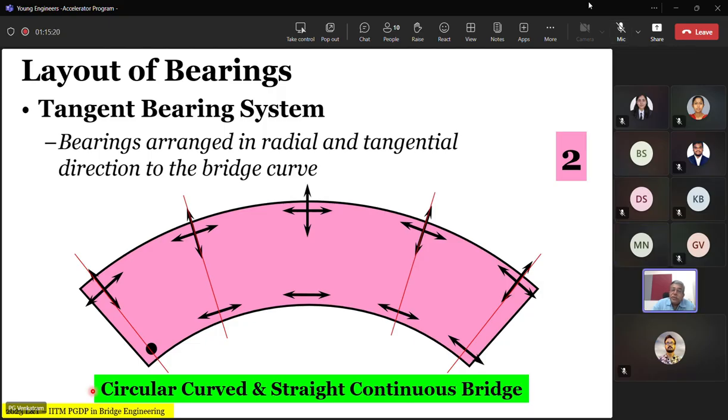No. Especially if you're doing concrete. Let me correct myself. Temperature you cannot avoid if you're doing steel, but if you're doing concrete, temperature and shrinkage, both the phenomena are unavoidable. That means there's always a volumetric change phenomena causing deformation. But on the other hand, live load is there in all bridges, whether it's concrete or steel. Therefore, a linear deformation behavior is there in all the bridges.